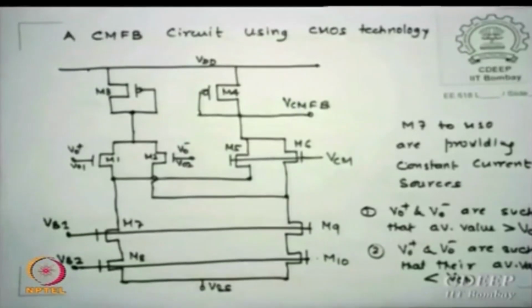Change in those currents will decide: if the diffamp stage is going down, it will actually boost the cascode stage. If the cascode stage goes down, the diffamp stage gain will increase, okay. So that the output gain remains constant with the CMFB, which I have not shown here, but that is why it retains higher gains and constant common mode value, which fixes higher SNRs, higher gains and stability.